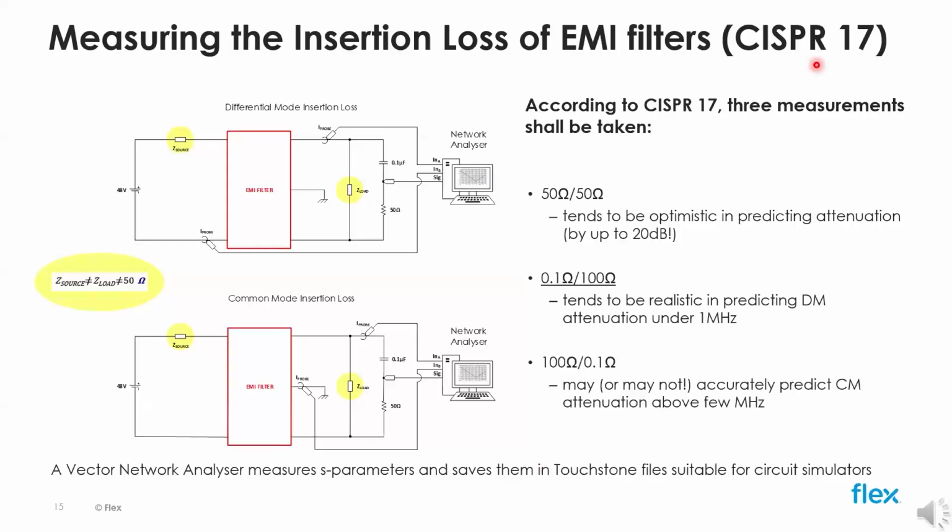Insertion loss depends on both input and output impedances, and the CISPR 17 standard requires measurement with matched and mismatched impedances. The rationale is to consider a real-world situation where impedances are either not matched or not even known. The resulting set of measures will better illustrate the filter characteristics. This is a major difference for the design of an EMI filter when compared with the typical design procedure of narrow bandwidth signal processing filter or wide bandwidth matched impedances RF filters.